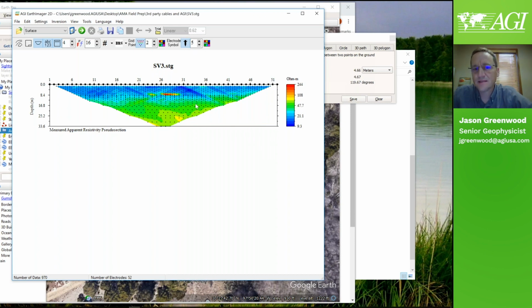And when I see noise like this, 9 times out of 10, it's the most simplistic thing in the system, not the settings of the SuperSting, not site conditions. It's the connectors and the cables themselves. So if you notice those spikes there, that's not something you would see from a pipeline, which would give you this V-shaped pattern, we call it pants legs or inverted V pattern. Let's look at another one. Again, that area has spikes.